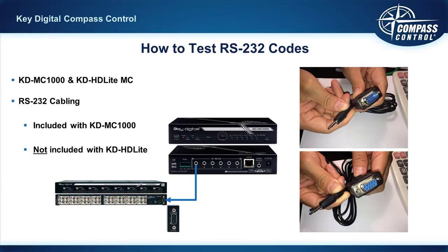Typically, the RS232 port on the device you wish to control is a female connector, and typically the control processor is a male pinout or 3.5mm. So that's why RS232 with male on one side, female on the other, is known as straight through wiring. And it all refers to the transmit and receive pins.